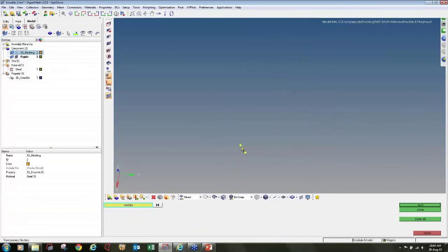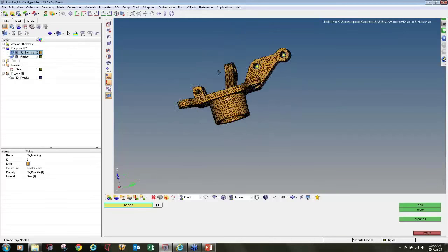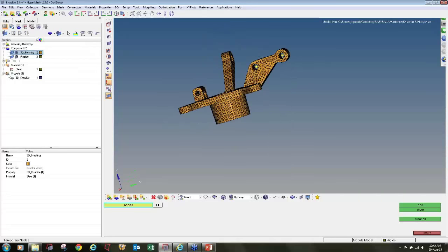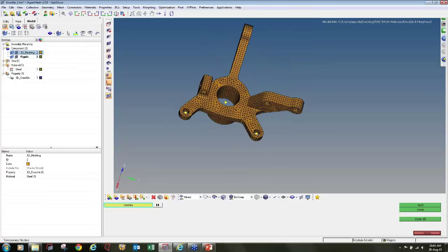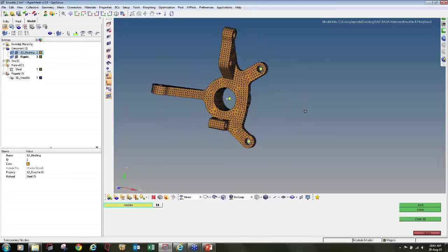So now I will turn this off and delete those nodes which are the circle center. So I will only have those nodes which are the center points of all my holes, where I have to apply either forces or constraints. So I have the center nodes of all these where I am going to apply. Here I am going to apply the constraint, these two and this one, and on this side I am going to apply all the forces.